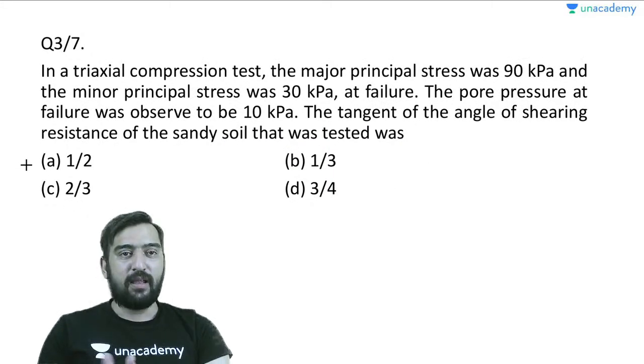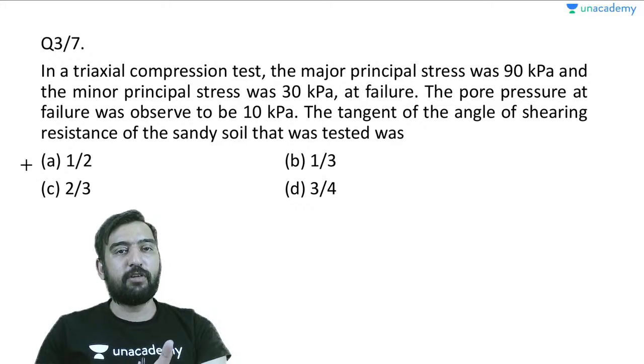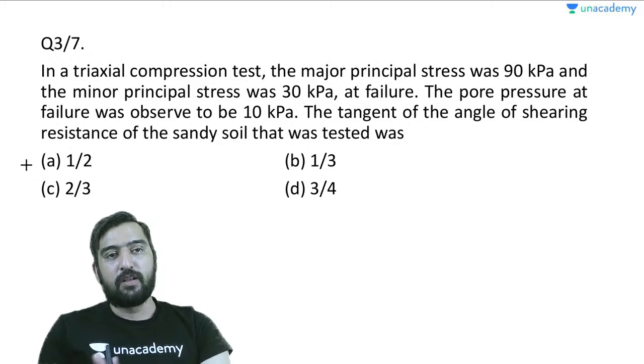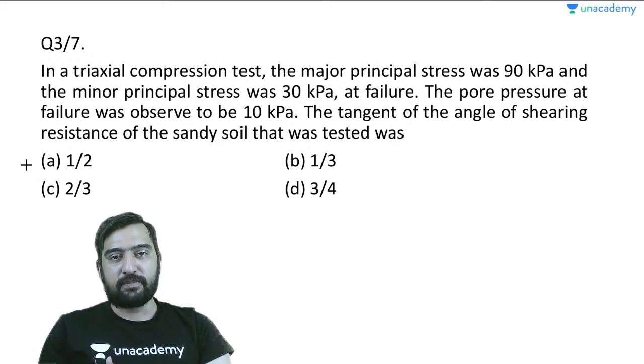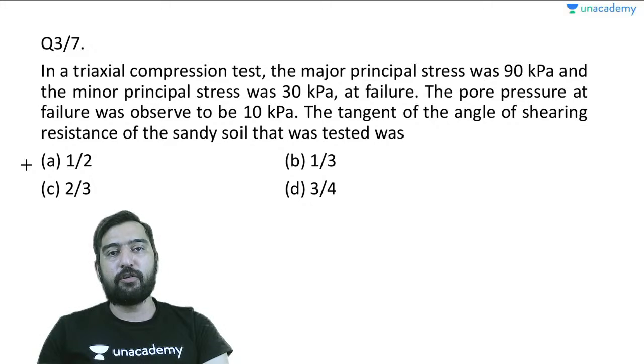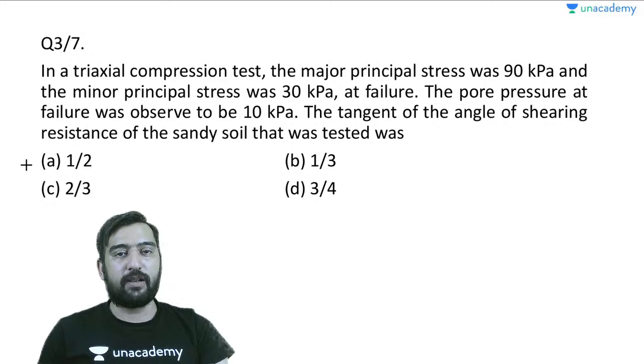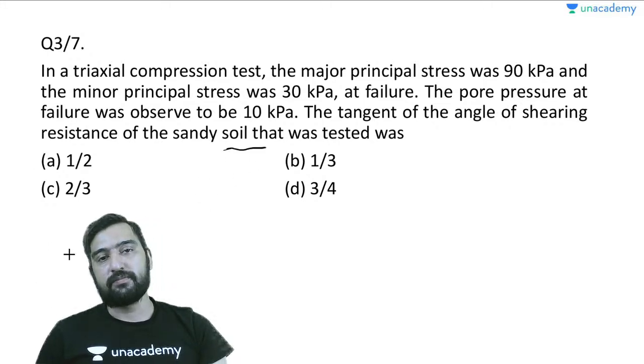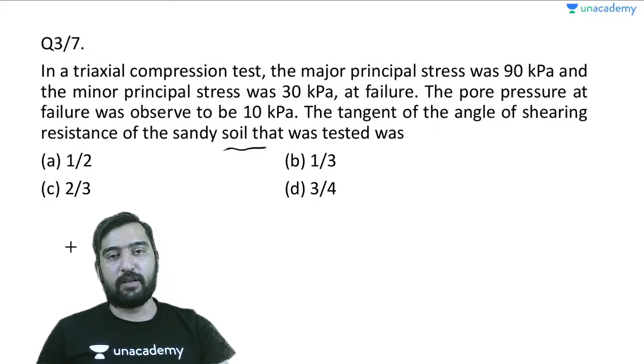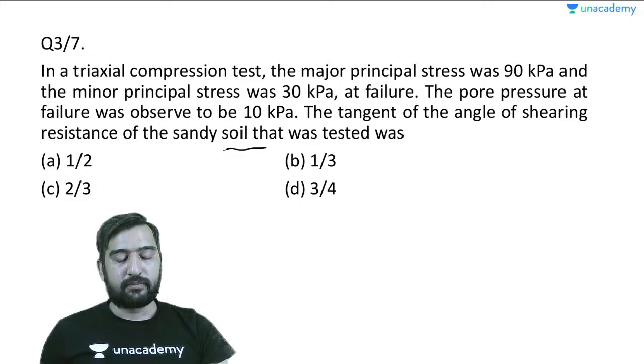It is not a very big test. I would try to wrap it up in 15-20 minutes. In a triaxial compression test, the major principal stress was 90 and the minor was 30, and the pore pressure at failure was observed to be 10 kPa. Now what is the angle of shearing resistance of the sandy soil that was tested? Is it clear?